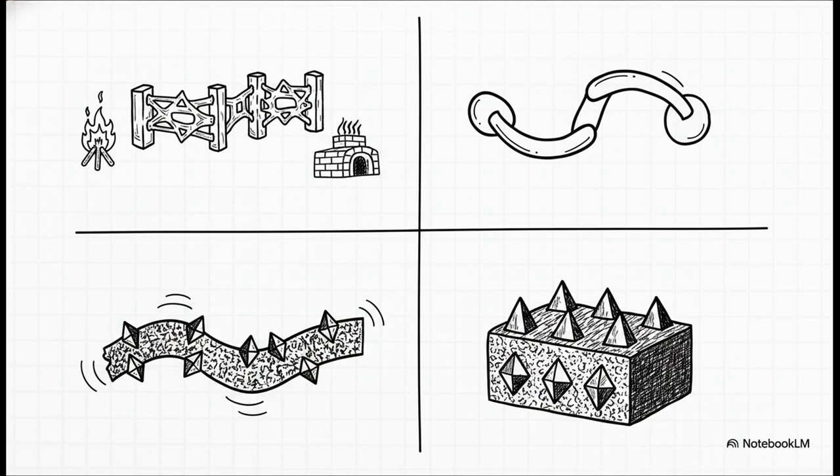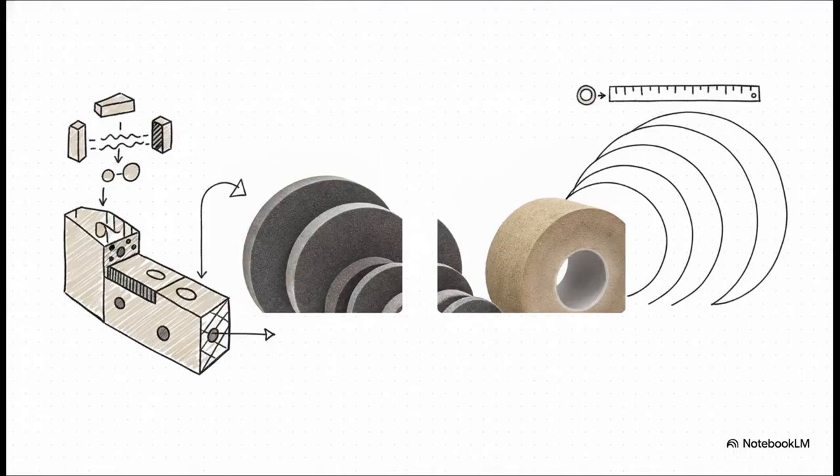There are even flexible rubber matrices for specialty blades, and solid metal bonds used specifically to hold on to ultra-expensive super abrasives like diamond. All of this careful engineering, the grain, the bond, the porosity, it all scales up into the perfectly balanced, highly structured wheels ready for heavy industrial use. We're talking everything from wheels just an inch wide to massive drums several feet across, all engineered with the exact same microscopic precision hidden on the inside.